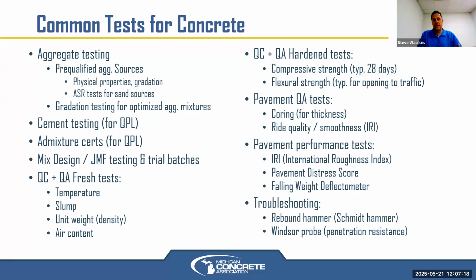Other materials, the cements themselves, and the admixtures, the chemicals. Those companies that supply those products maintain their product on the qualified products list, QPL, that MDOT maintains. They have to periodically submit samples as well, or submit test results with their materials to prove that they are still formulated properly and working and fulfilling their intended purpose at the given manufacturer recommended dosage ranges or that type of thing. So that is periodically done as well.